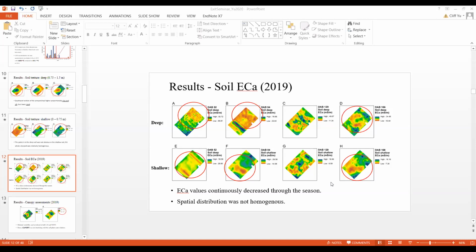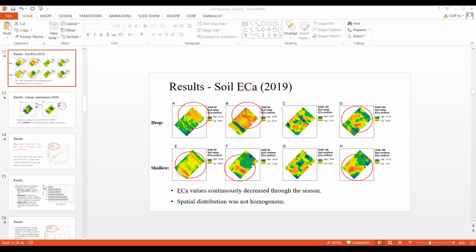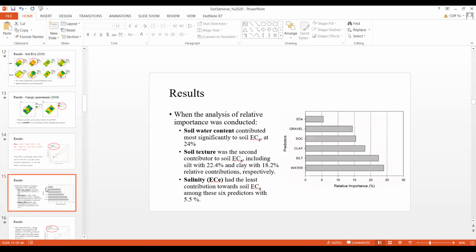Because, as you showed with that nice table, the raw electromagnetic conductance readings off the EM38 fold in a whole bunch of parameters, salt, water, soil texture, that provide a unique integrated reading that can help with overall water and salinity management.